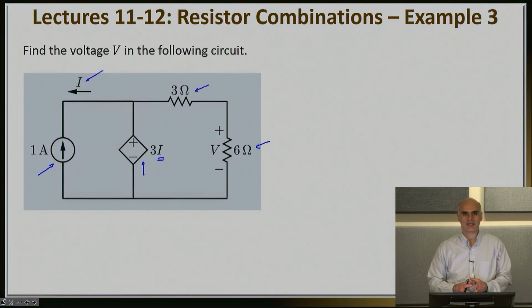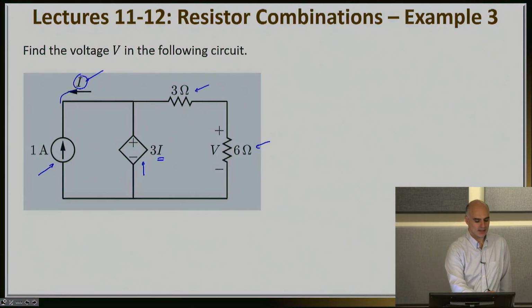In more complex circuits we'll see later on in this class, we may have to spend a little bit of time and do some thinking to find out exactly what the controlling variable, I in this case, is equal to. But in this example, things are quite simple in the sense that this current I is directly flowing into an ideal current source.